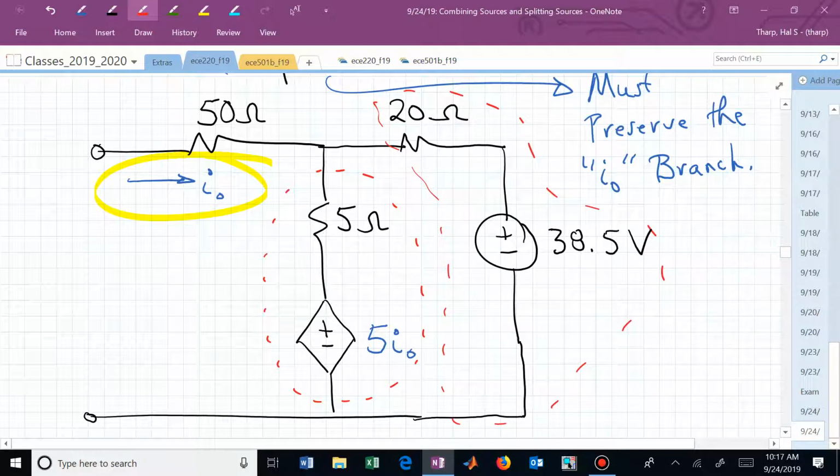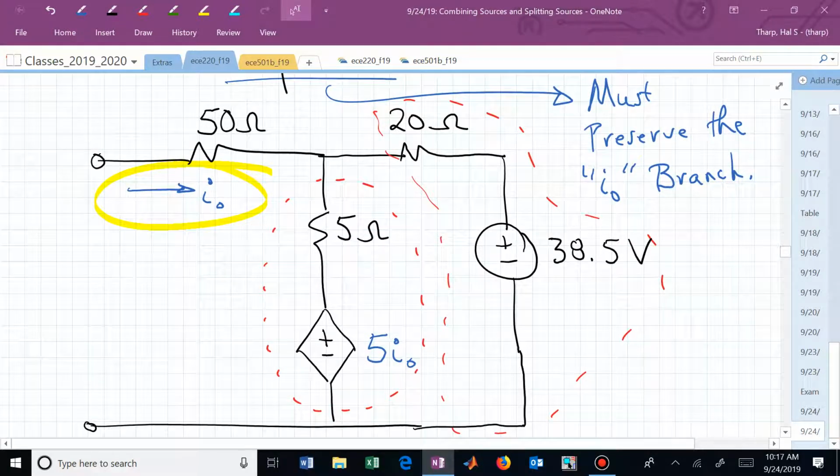That's another Thevenin. Together, what are they? How are they connected? Can we just combine these two immediately? How could we combine voltage sources if they're in series? Are these two in series? These red blobs? Those sources are in parallel, are they not?